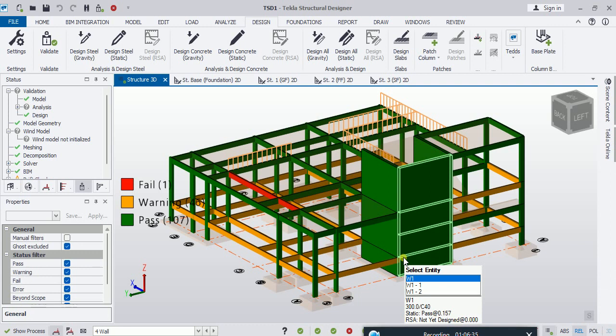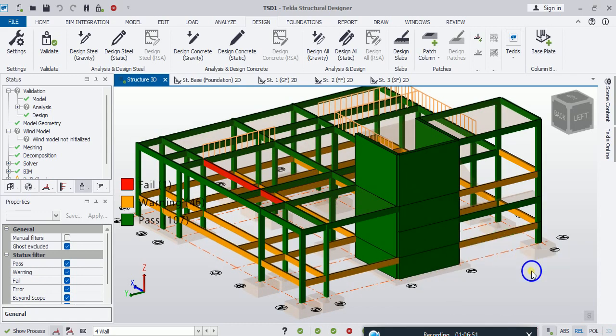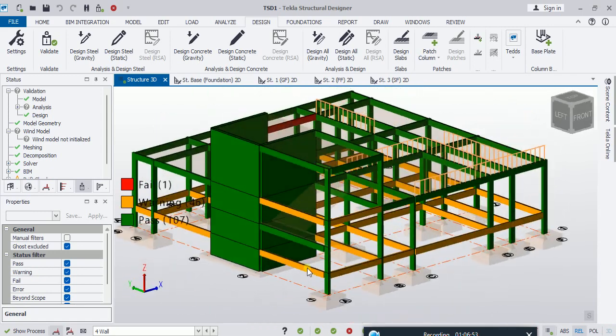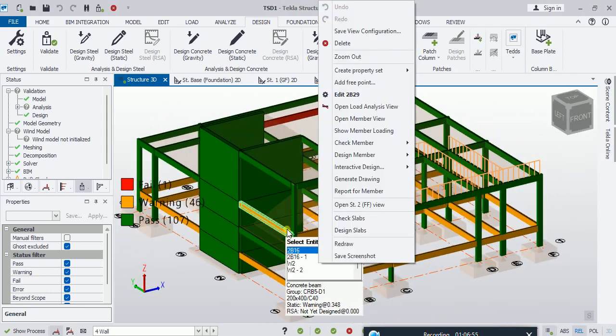Okay, because here you are not modeling the slab, so the software will not understand that anything is taking it. So it will have some tension. You can ignore this one because in reality you are doing a slab. Are we clear? As long as it's not failing. So for blend beam you can ignore, but the other areas you can modify.